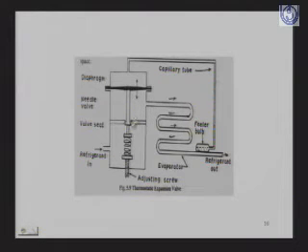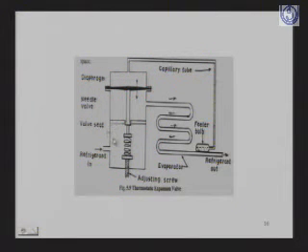If evaporation is less, then it will allow less refrigerant to flow inside. So all the refrigerant will come this side, but depending upon the outlet evaporator temperature, we try to control it through this expansion valve. So this expansion valve serves two purposes. It reduces the pressure, and simultaneously it controls the temperature. This is the advantage of this type of expansion valve.